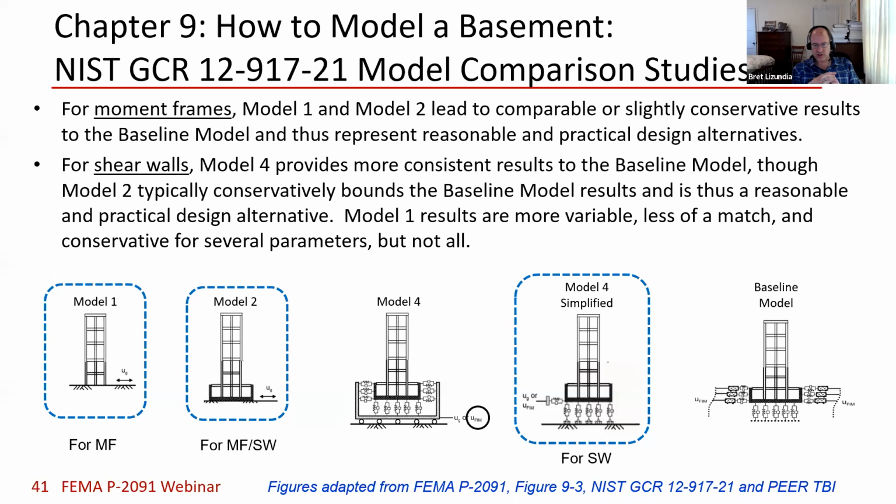If you actually got the full value, you're moving an inch or more, and a stiff concrete shear wall foundation would be trashed in order to do that. So in order to actually mobilize meaningfully the surrounding soil in a situation like this, it's not going to happen. And so that model where you're essentially ignoring the soil is a reasonable approximation.